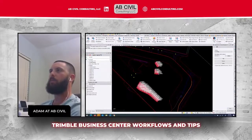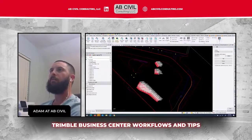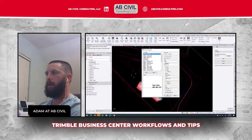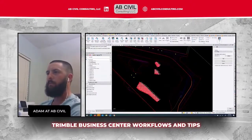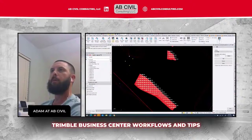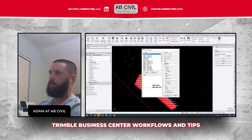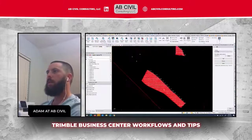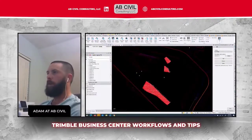So the text is way too big, so I'm going to go up to drafting, text style. I'm going to go down to my cut fill labels, and yeah, it's way too big. I'm going to make it 0.04. Even that was too big. 0.025 maybe. Yeah, that's good enough. So now I just made a cut fill map out of what started as three initial surfaces.